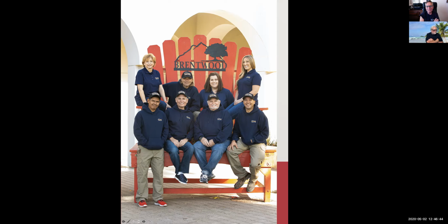Carolina writes, what type of non-slip tile do you recommend for bathroom flooring? Carolina, take a bottle of water with you, go to a tile store, pour some water onto your fingers and run it across the tile. If it feels like you're ice skating, put that tile down and find something with a little more texture. It'll be a lot more slip resistant.